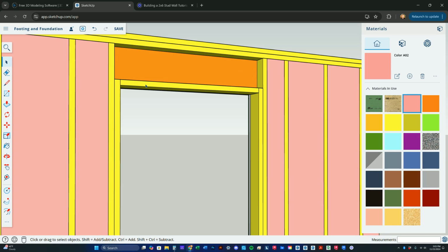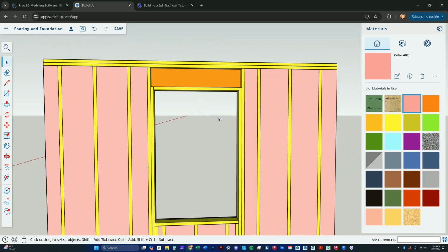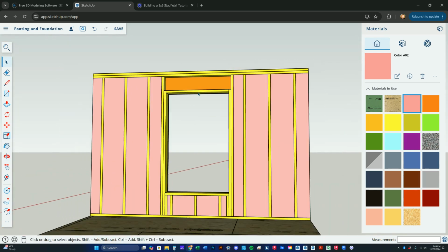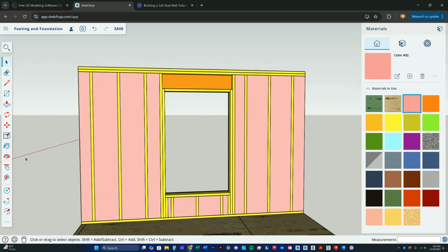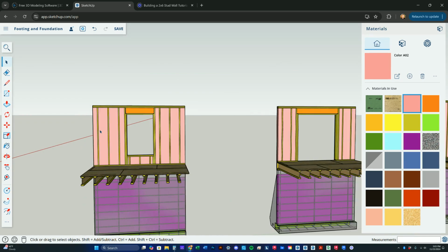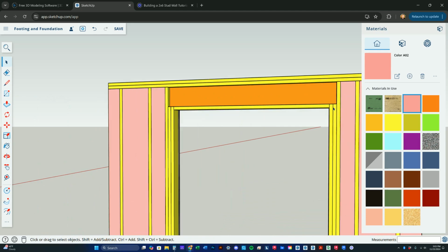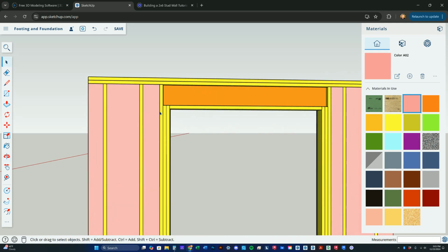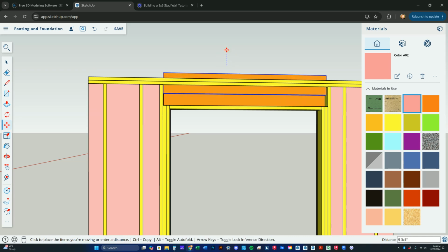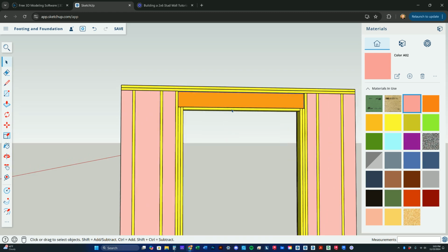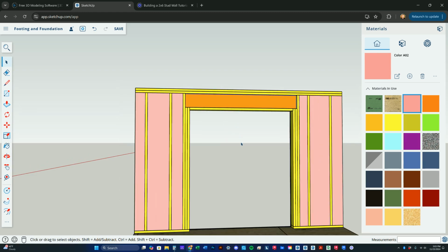And this is a 1.5-inch filler to just bring it down to where I had said to put the rough opening, which is at 6'10" above the bottom plate. So to repeat that, for your door opening, this called for 2 jacks and a king. So you do basically the same thing as you did on the window, 2 jacks and a king. You put your header right up underneath, and this one requires 2. So let me move this up so you can see there are 2 in there. You'll bring it down to 6'10" above the subfloor with this to shim it down.